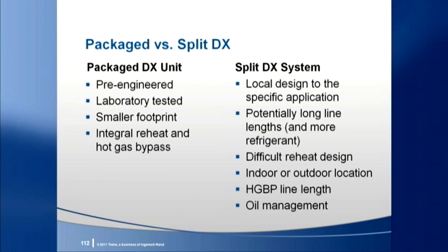Refrigerant line length is always an issue for splits, and often needed requirements for both hot gas bypass and reheat make the number of lines, length, routing, and cleanliness important factors to the success of a split system.